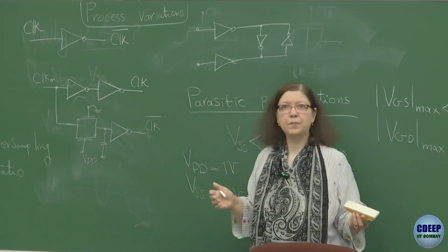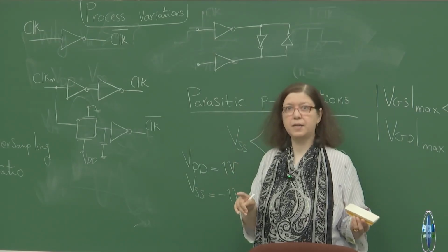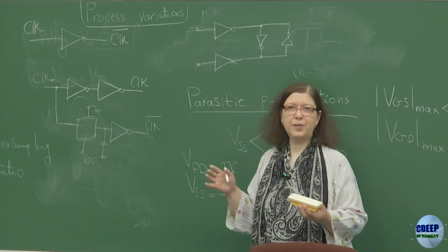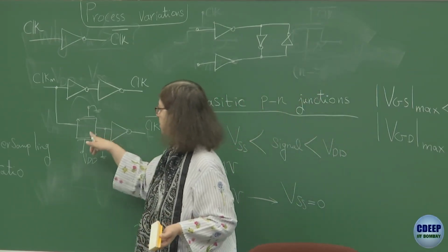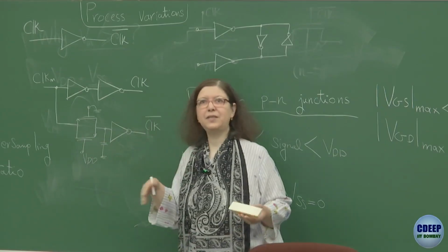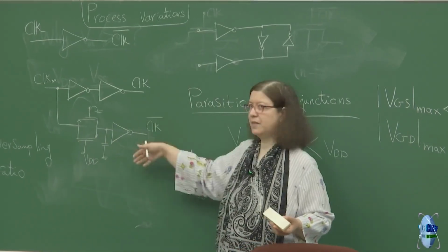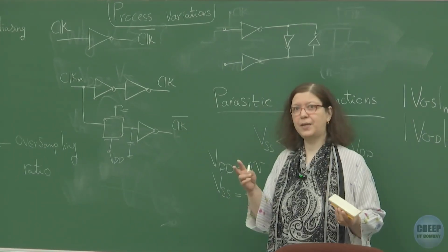It's still going to be subject to process variation, yes. But why, for example, does Razavi say that this could be one of the solutions? The reason is because you don't have 3 inverters here. If you have 3 inverters, you will end up in the same problem of 1 inverter difference between the 2 paths, and again the mismatch due to that extra inverter.